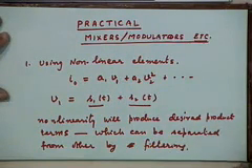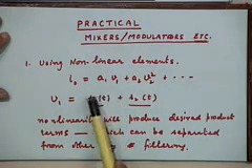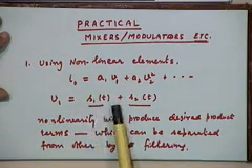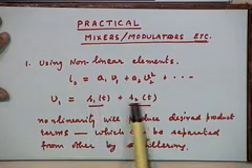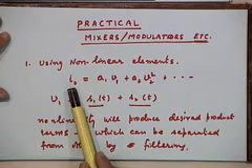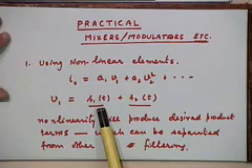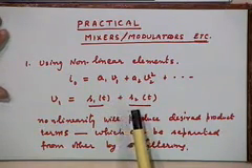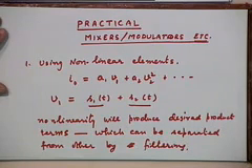So based on this principle, we can see that if you apply the input voltage, which is a sum of two voltages, one of which is what you want to multiply basically, because of the nonlinearity present, the output current would have some product terms, right. And if you can ensure that by suitable filtering you can take out only the desired product term and reject all other components, the purpose is achieved, right. So I will leave this at this point. For practical circuits based on this principle, I would like you to refer to books.